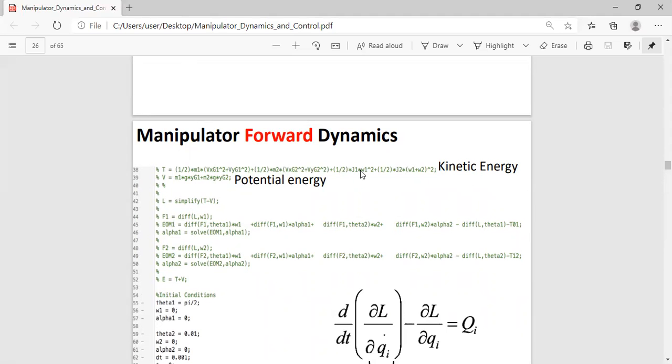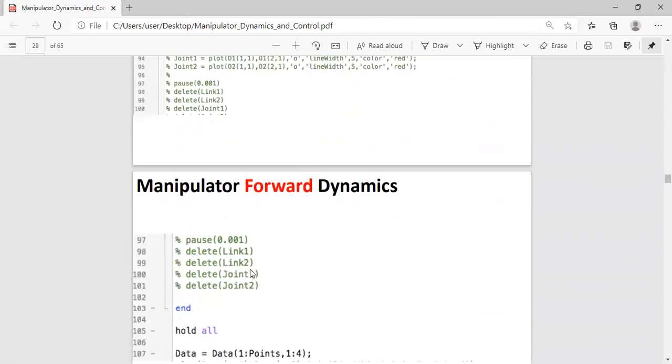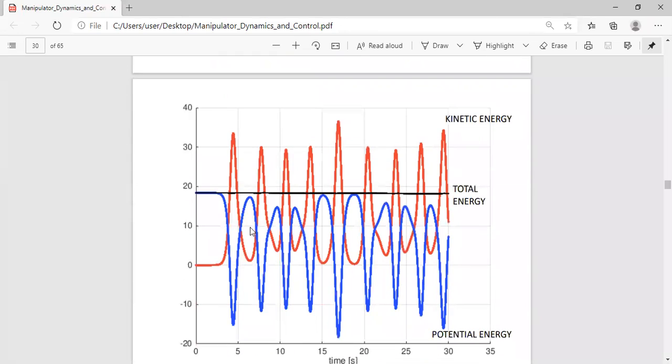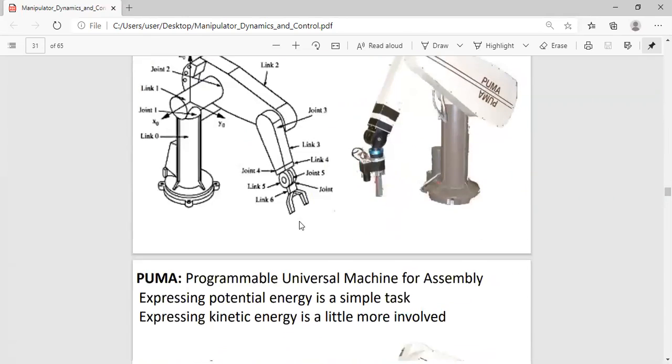Well, actually, here we did incorporate one of the rotational components. Here we were dealing before with a planar robot, as you remember, so we don't have the other two components. But when you have a PUMA type robot, you have a yaw on the first axis, then you will end up with some weird rotations on the other axes. So you would need to incorporate that. So this is fine if you're not considering rotation about the base axis. But to be able to consider robots with articulated arms or articulated wrists, where you have perpendicular axes of rotation, you would need to do that.